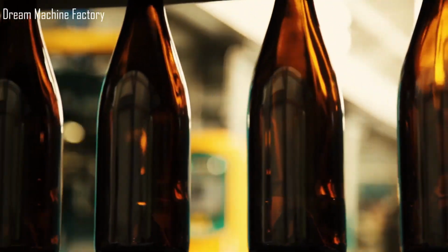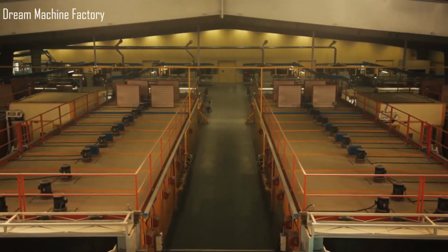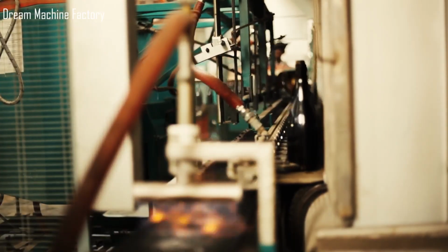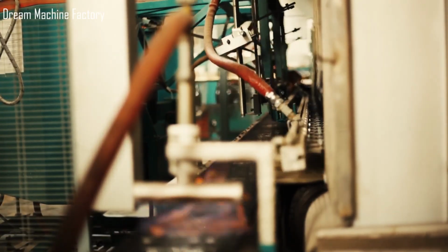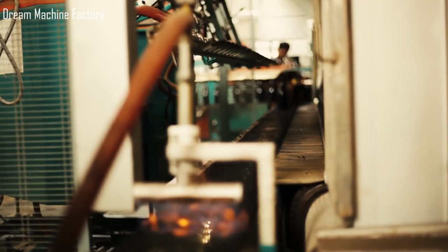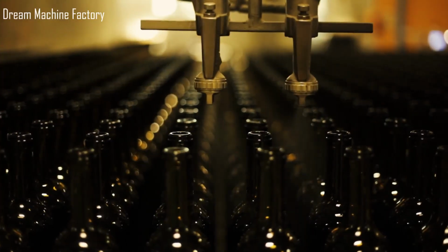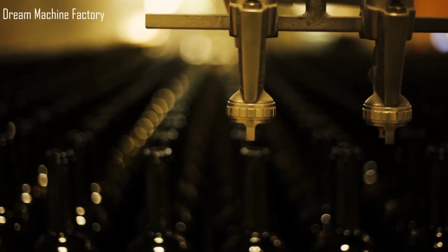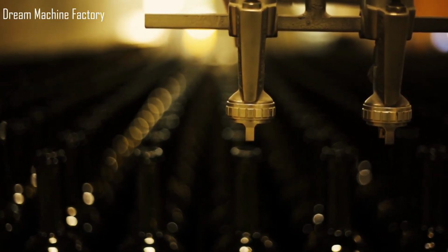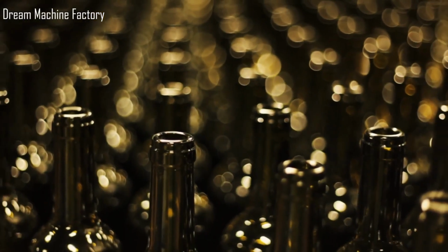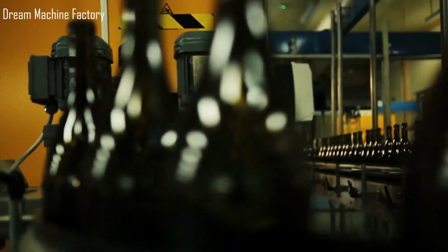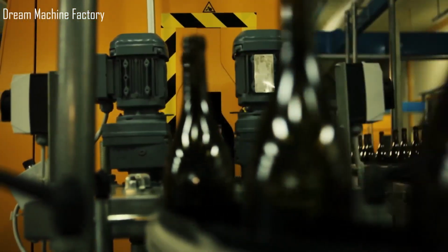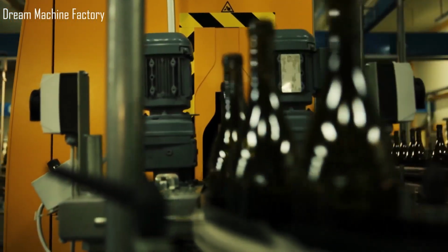bottles receive a cold treatment to increase surface friction, reducing the risk of scuffing and improving handling during transportation and bottling. Each bottle is subjected to rigorous inspection. Automated systems check dimensions, bore diameter, glass thickness, and detect defects or brittleness. Bottles failing to meet strict quality standards are destroyed and recycled. Once approved, bottles are stacked on pallets, shrink-wrapped for protection, and prepared for shipment.